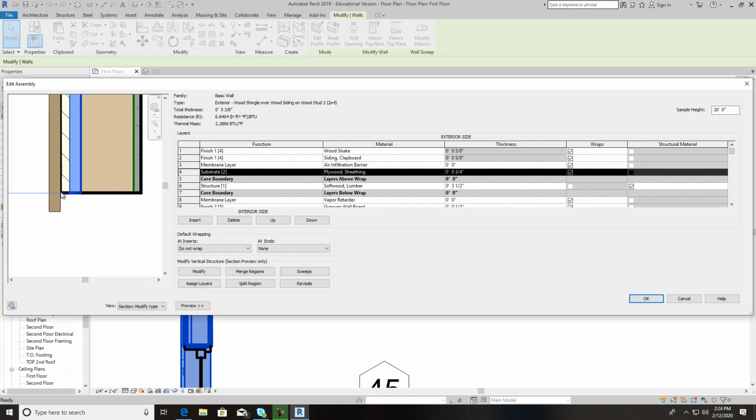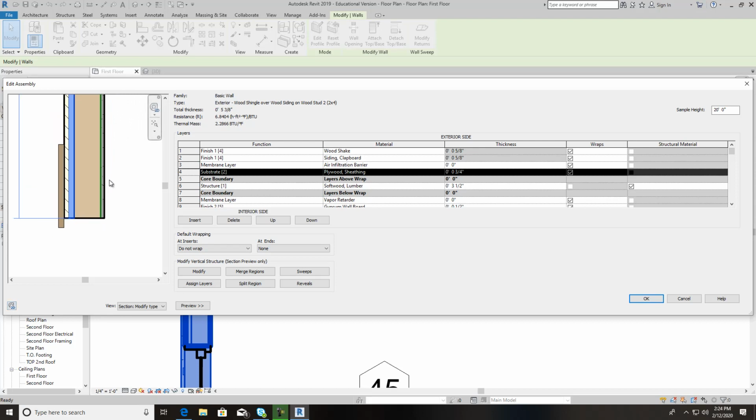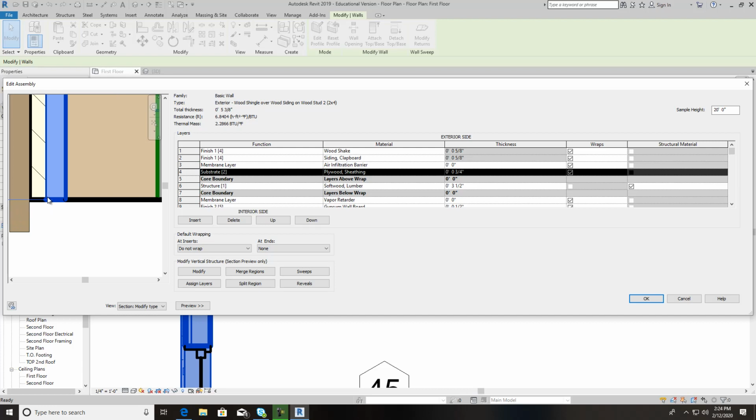Instead, if you had a block that was right here, and act like this sweep isn't here, if your block was sitting right there and it rained, it has a good chance of going right back underneath and rotting your wall studs and your floor. So that's no good. So that's the reason you want to have this right here as your measurement point.